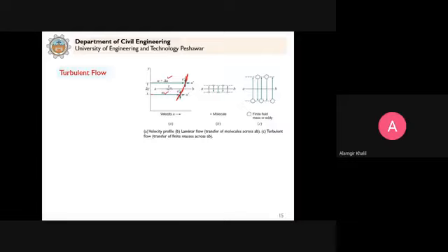So now whenever a fluid particle which is moving here enters into this fast moving layer, what will happen? It will try to slow down this layer. It will bring a velocity change as long as the velocity profile is changing. Remember, we are talking about that. So it will try to slow down this layer. And any particle which is here and enters into this layer will try to speed up. So this is how the momentum transfer occurs.